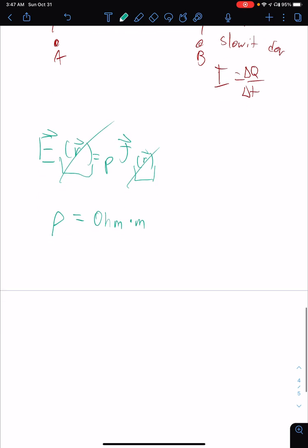And if we go to our resistance equation for resistivity, which is resistivity times L over A, if we just wrote out the units and wanted to see how they canceled, ohm meter times a meter over meter squared. So, oh, 1, 2, 3, we get ohms.